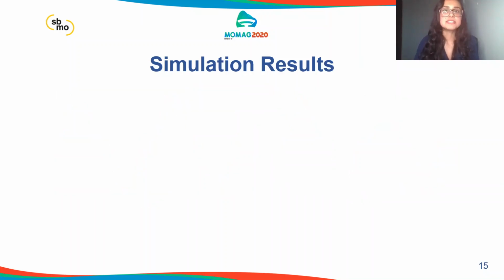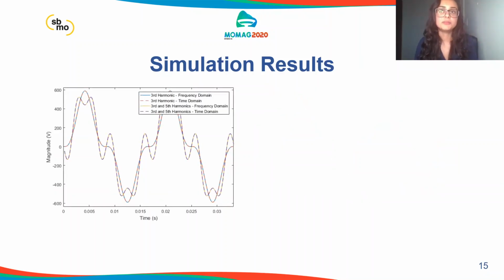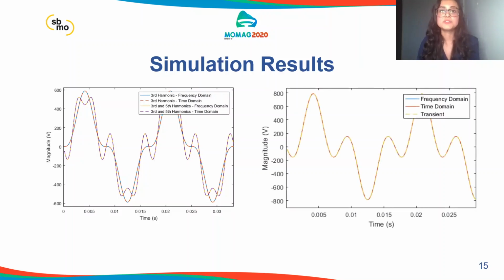In order to present the injection of one more harmonic component in the system, an independent source was included at the 50th harmonic of the fundamental frequency of the circuit, as presented. Also, in the second figure, we can observe the effectiveness of both approaches with the inclusion of the third and 50th harmonics in the system, from the comparison with the transient simulation.